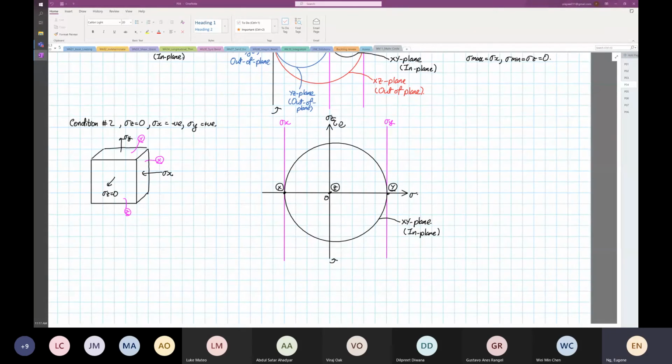If you look at your shear, it's evident that it has the largest shear. So if your stress condition is this way and you happen to just analyze 2D, you're lucky. It happened to work. So this is your shear max in the XY, which is also equal to your shear max. It's the bigger circle, and this is your in plane.